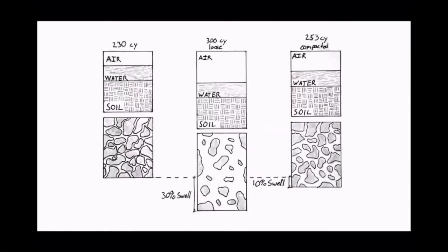All right, so that's where we get this 30% swell between the 230 cubic yards in the site and the 300 cubic yards loose. I know this is not difficult. Just trying to do it enough times that it becomes second nature should you see a question like this on an exam. All right, this is the next problem.